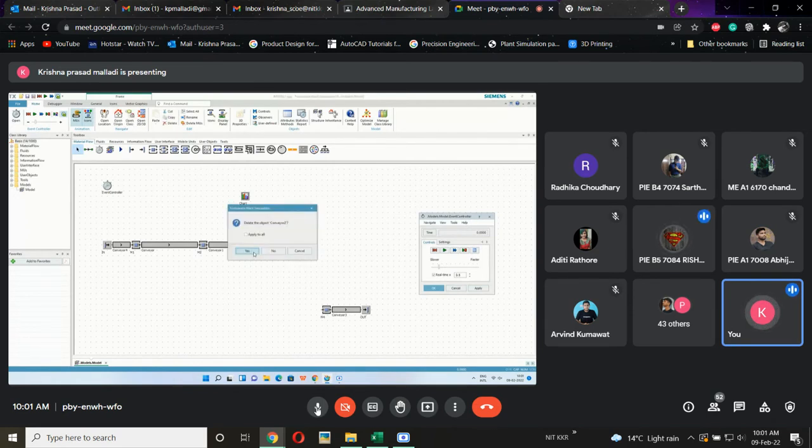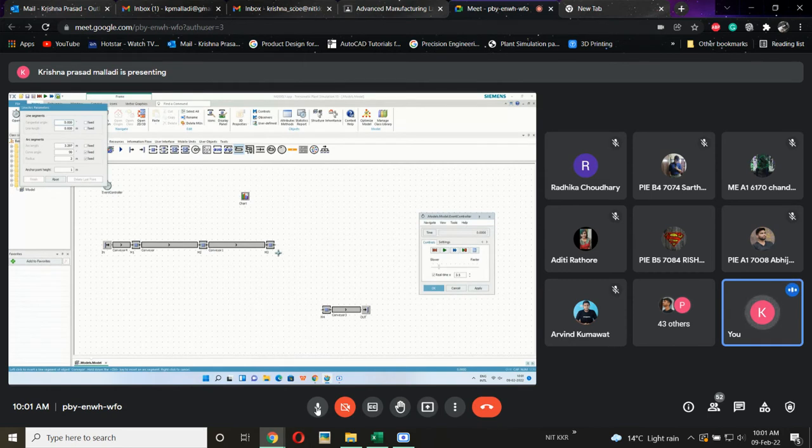Or else if you want to continue, then same thing. Conveyor, click on the first object, then hold control, and you will have curvature in the downward direction. Click on the downward direction, and if you hold control again it will give me like this. If you release the control button, then again it will show me straight lines. So once my conveyor is done, I need to press escape.